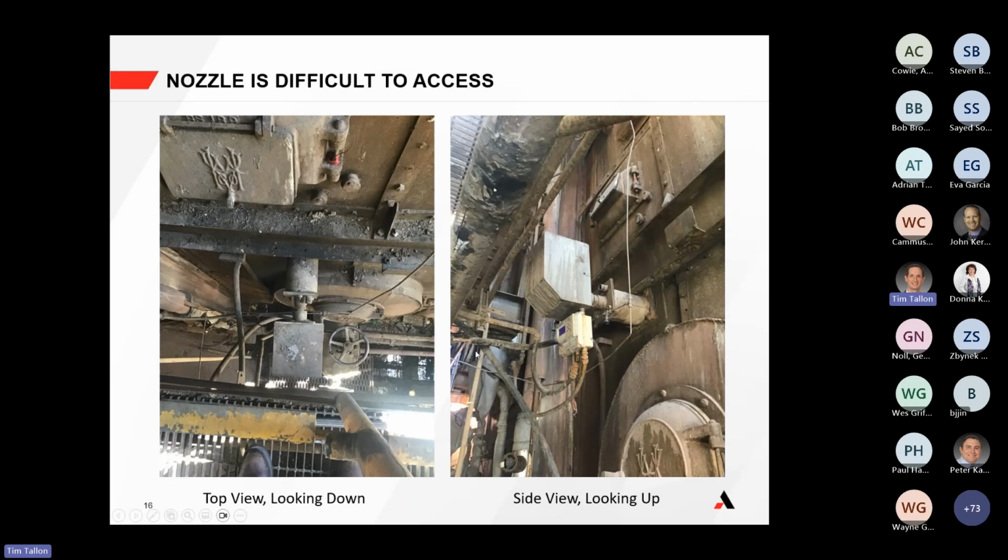Some examples that come to mind would be where you have the grading right here, and the process flanges and the heater flange are right underneath it. But then on the next platform underneath, it's too high to access. In this case, the nozzle might be too difficult to access. We might recommend remote mounting in this case.